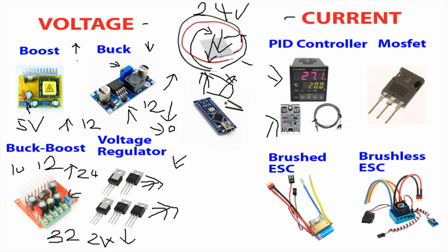Now obviously the thermal resistance, or how well the TEC conducts heat when it's off, is not particularly great, but if you have a large temperature difference, you'll find that it will quite conduct the heat back. So much so that in thermoelectrically cooled computers at idle, you probably don't even need to have your TEC on and your computer will be stable, and that's what I have done in the past.